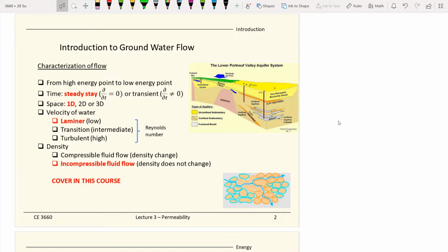and we will just focus on the geotechnical applications. The two main geotechnical applications we try to achieve in this lecture are, first, to be able to calculate all the heads that we talk about: the total head, elevation head, and potential head. This is one of the key things we try to achieve for this Geotech 101 class. Secondly, we will learn how to characterize the hydraulic conductivity of soil. Those two main objectives are the major work scope for us geotechnical engineers.